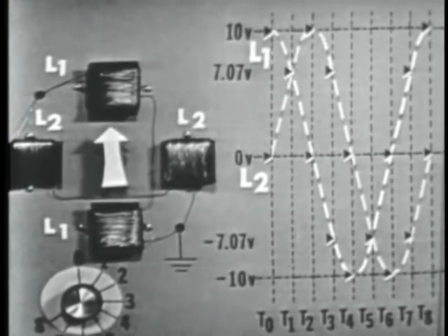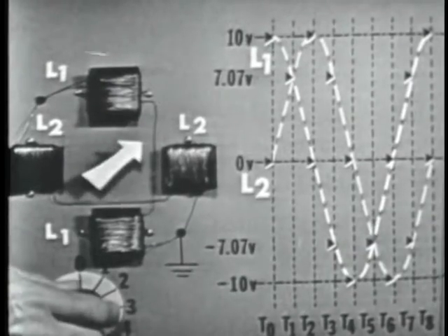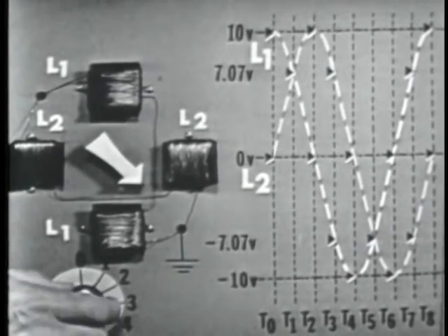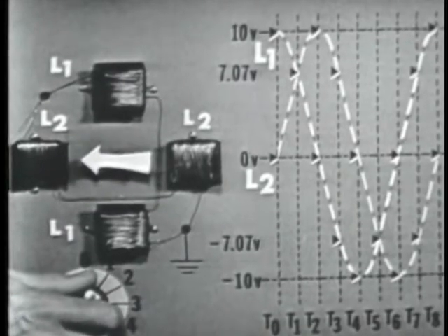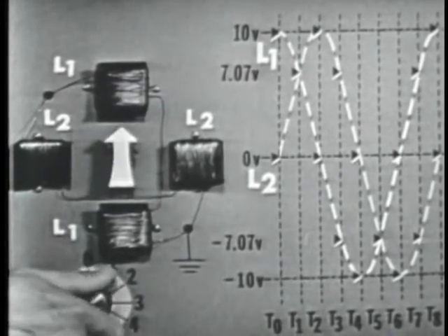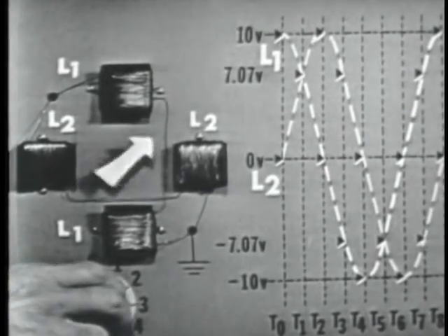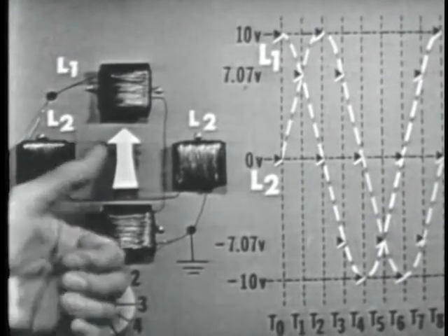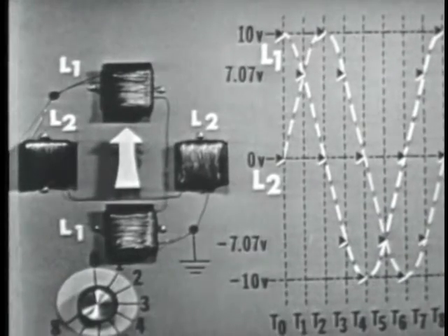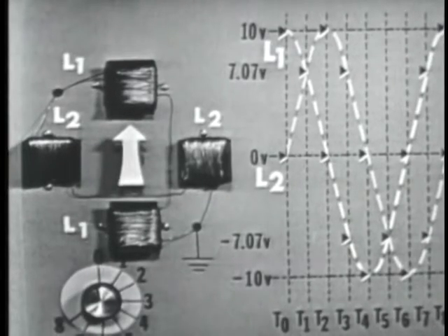All right, you can have it. Item 7 shows you how one complete revolution of the magnetic field is accomplished by applying these out-of-phase voltages to the stator windings. Now, you can study this very, very carefully so as to fix the principle in your mind. Which was, by the way, we might point out, Tom, once again, that you can apply the left-hand rule to all these coils and prove precisely what we've said, right? We can develop a rotating magnetic field.